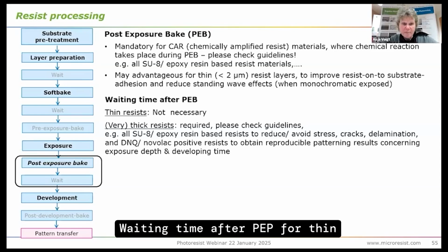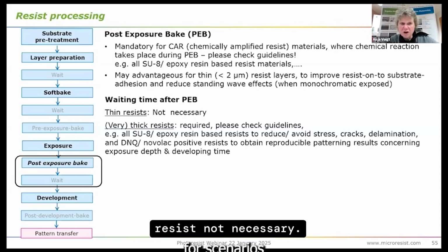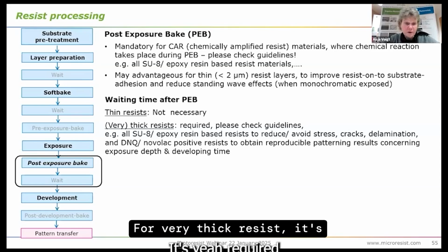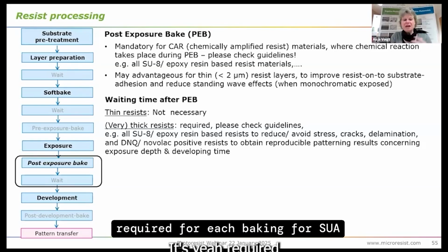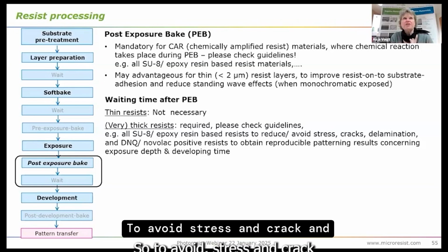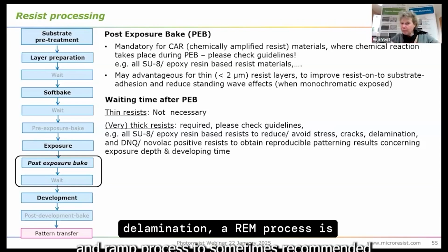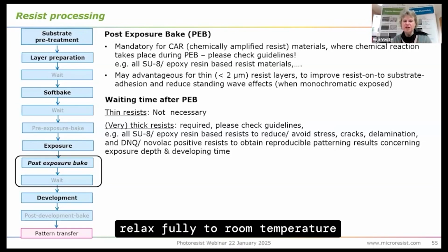Waiting time after PEB for thin resist is not necessary. For very thick resist, it's required after each baking for SU8, to avoid stress, cracks and delamination. A ramp process is sometimes recommended, and let it relax fully to room temperature before starting the development.